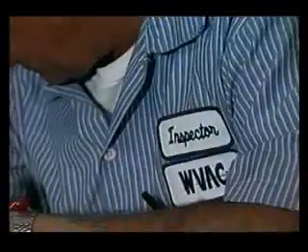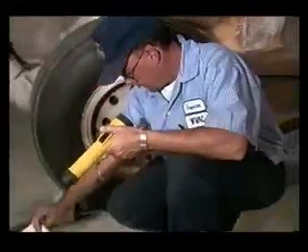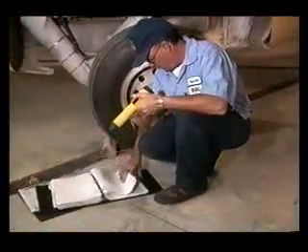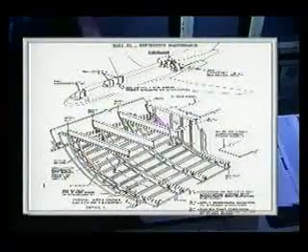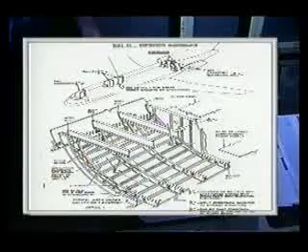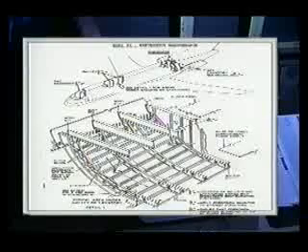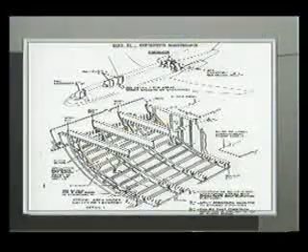The next step in your program is to map the results of the baseline inspections to record the aircraft trouble spots. These aircraft maps will help the maintenance department to design aircraft inspection programs. Shown here is a sample of such a map from a larger air carrier corrosion control program. This map will be used as a guide during all subsequent inspections and scheduled maintenance activity. This guide should indicate the inspection frequency and any treatment or prevention actions to be accomplished during scheduled maintenance.